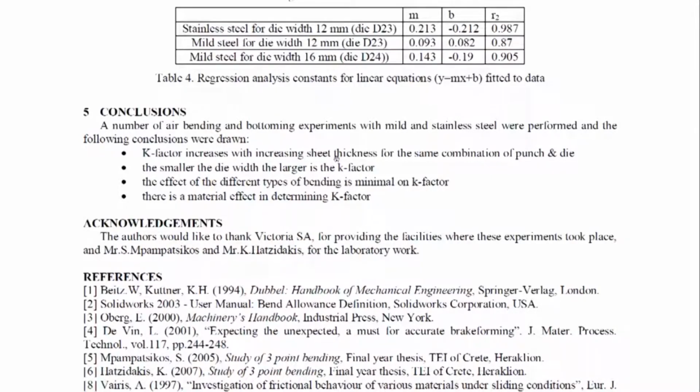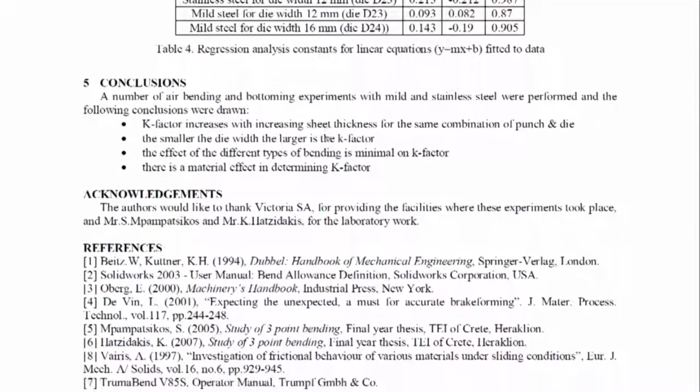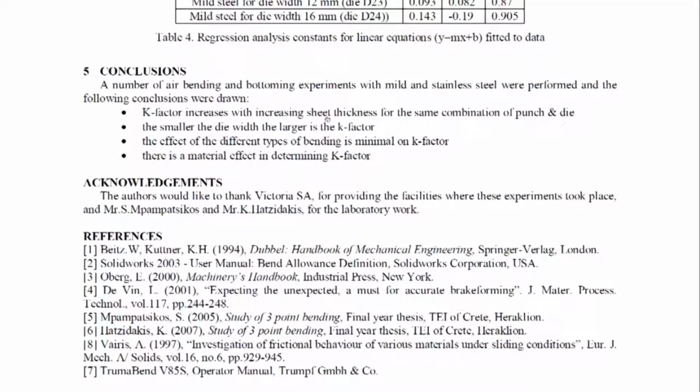So, you can always go about and try to understand these things, to see in case there is any mistake. So far we are assuming that all the machines are maintained well, there is no gap or shake between the punch and die, alignment is fine, and whether the forces are centralized or not. If you are sure about these conditions, you can work on all these things and end up with a very convenient, reproducible width of blanks. Once you have blanks of reproducible width, things will work very, very well.